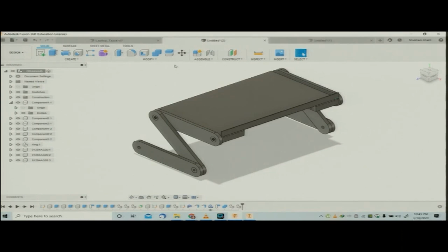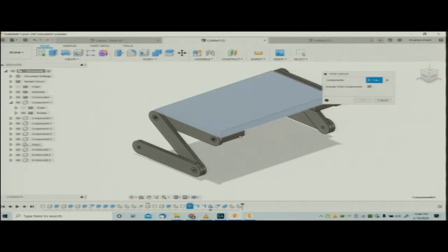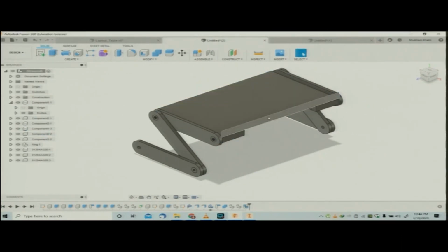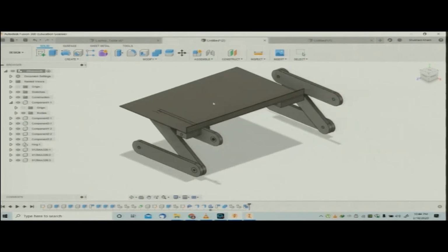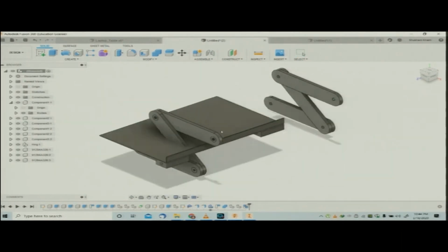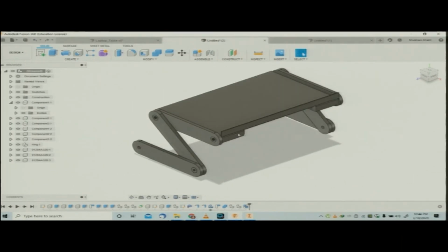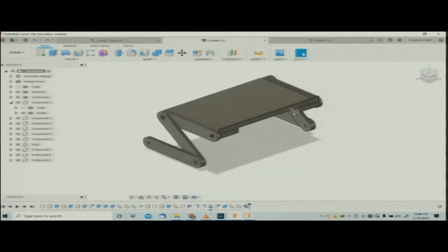Now I will start to put joints here in the assembly. Let us make some rigid joints. I need to make the sheet metal and the hinge support a rigid body. Now this has become a rigid body. Whenever I move this, it has become a kind of permanent joint here. Wherever I move this body, both bodies are now one body. They were created separately, but they have become a rigid joint here.